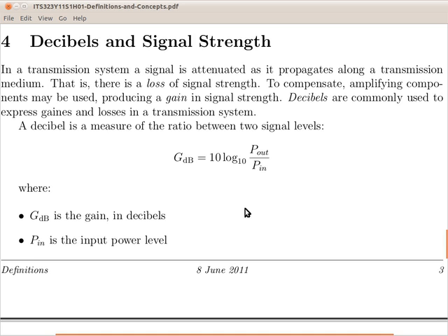So, an example, our input power is 1 watt. We've got an audio amplifier and some system that produces 100 watts on output. So it's an amplifier in this case. It has some gain. The absolute gain will be 100. No units, it's a ratio of two power levels. So this is 100 times larger than the input. We increase the signal by a factor of 100.